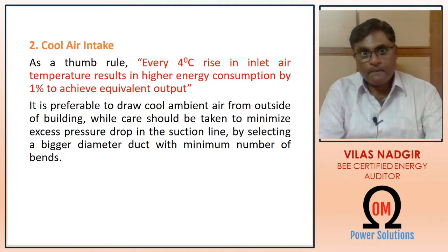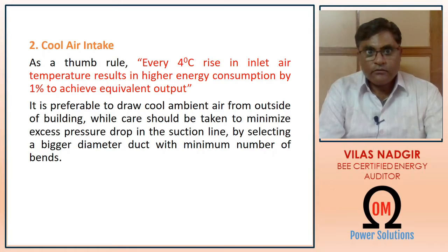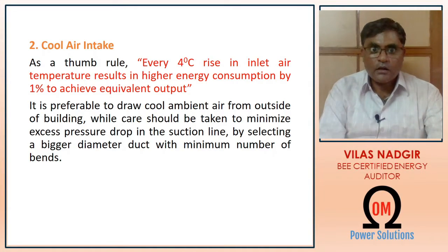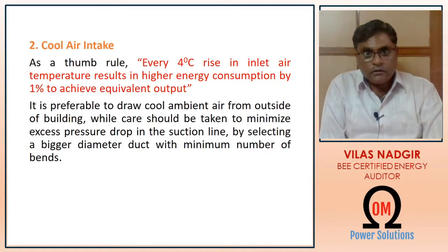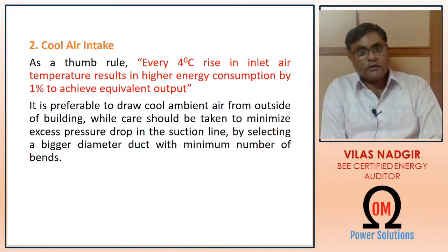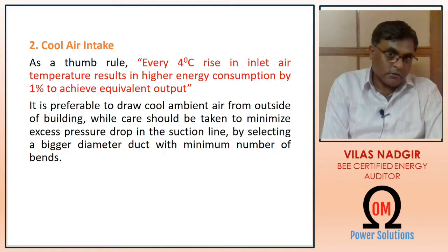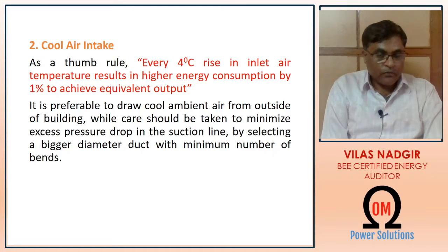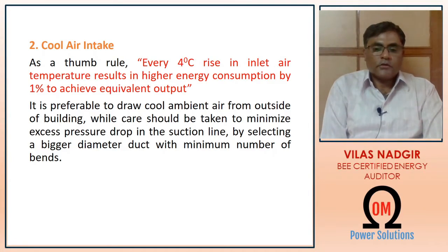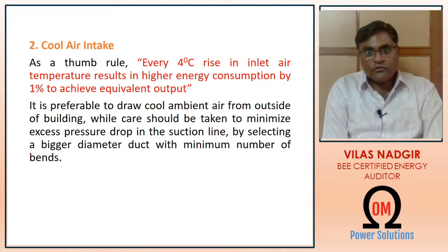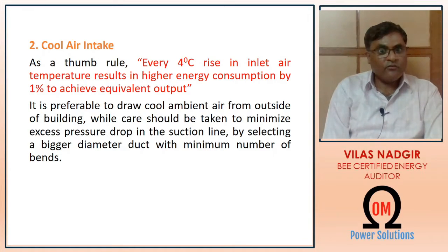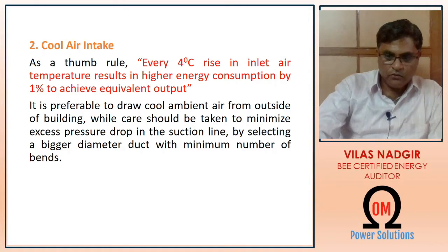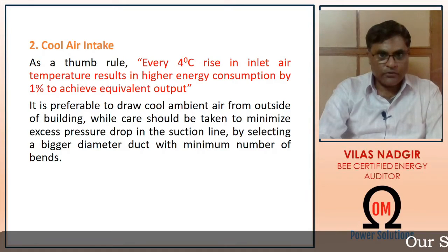Cool air intake. We have to try to take cool air from the atmosphere, because as I told you earlier that cool air has less volume compared to hot air. As a thumb rule, every 4 degrees centigrade rise in inlet air temperature results in higher energy consumption by 1% to achieve equivalent output.